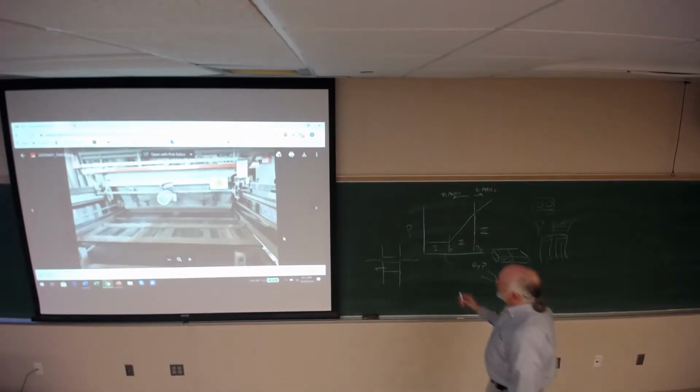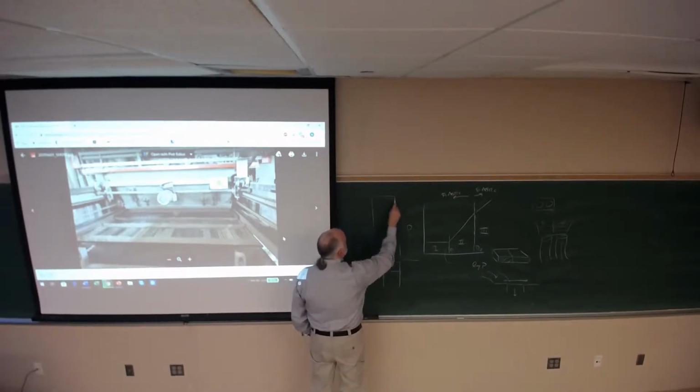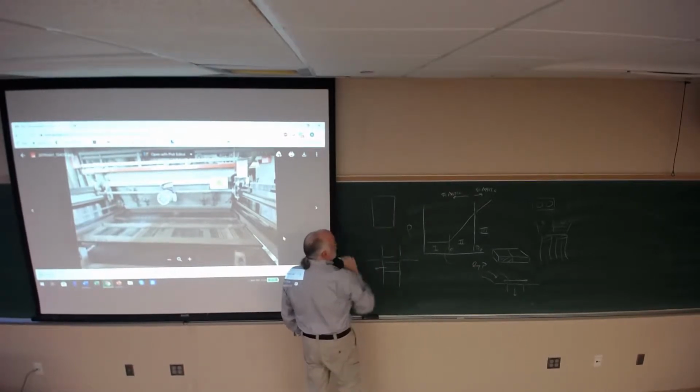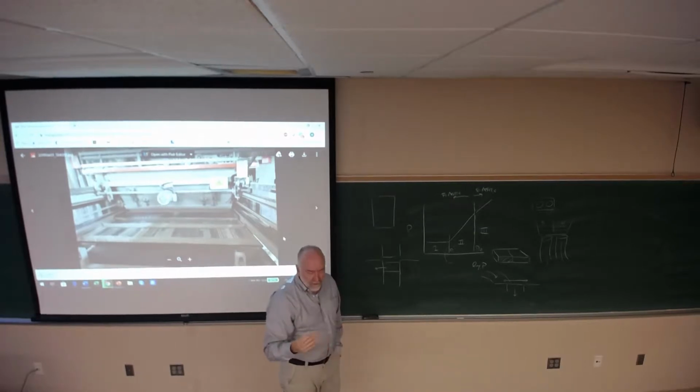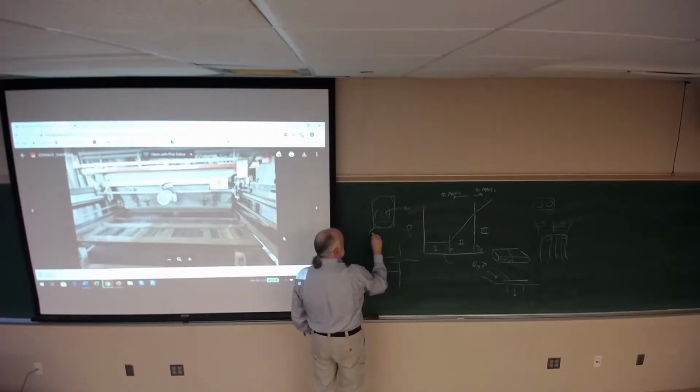If you look at the classic pressing situation like this, they press a cylinder, right? And then they would look and they go, look, we have density gradients. A classic image comes out of Reed's book. You have low density in the center. So this is the low density here in the middle, and then you get your highest density on these corners.